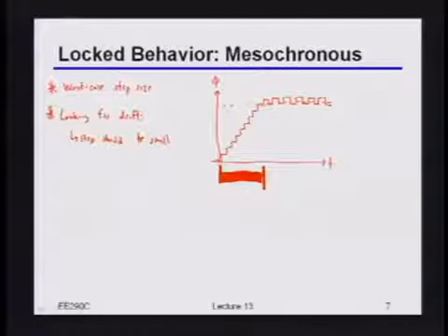And also, if I have some big noise event or some big errors, I'll just very quickly, quote unquote, correct for them. But of course, at the same time, if I have a really big step, then even when there's no noise whatsoever, I'll just be jumping around with a really big magnitude, right? Okay, so indeed, if I'm in a mesosynchronous system, I'm going to tend to make the step size extremely small, okay? And in fact, I may even run the CDR just for some short period of time, and then turn it off for a while, turn it on again maybe a millisecond later or something like that, just fix whatever errors were there, turn it back off, and so on and so forth, okay? And obviously the reason for doing that is it saves you some power.